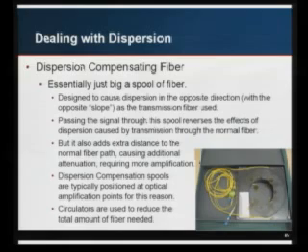And typically, they use circulators to give this a second shot, so you may run the signal through the fiber twice to use less fiber and accomplish the same amount of dispersion compensation. But basically, that's all these things are inside. They're boxes with a bunch of fiber in them, and they may charge you thousands of dollars for them, but this is all they are.